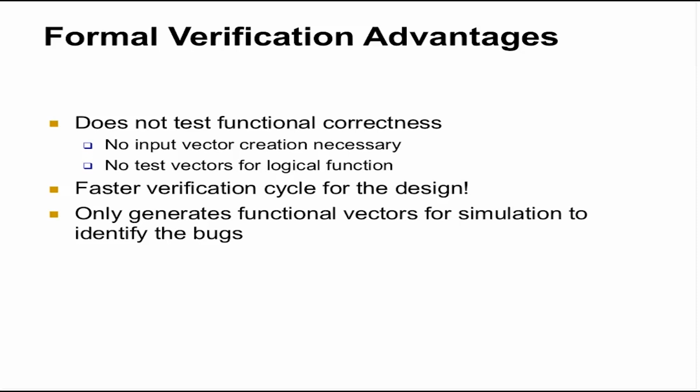So how does the flow work? It does not replace dynamic simulation, because in the first place the RTL has to be verified with some kind of vectors, whether random, specific or deterministic. There has to be some testing that verifies that the RTL matches the specification. Neither STA nor formal verification is trying to replace that.